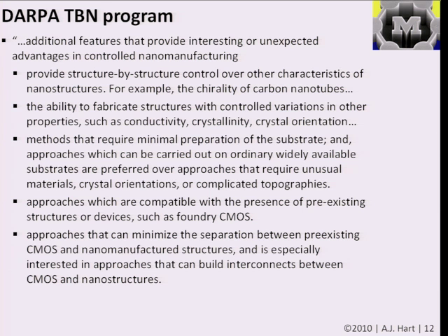It's kind of like what happened in the field of MEMS, or microelectromechanical systems, where in the MEMS field, integrated circuit fabrication technologies, thin film deposition and etching, were used to create mechanical and electromechanical structures. And then for things like the first MEMS devices, like accelerometers that are used for airbag deployment, for example, nowadays, you have a mechanical device, an electromechanical device, a moving mass that moves in an acceleration field, and that's surrounded by all the circuitry, the low-noise electronics that measure the signals from the motion of that, and that's all made in the same process.